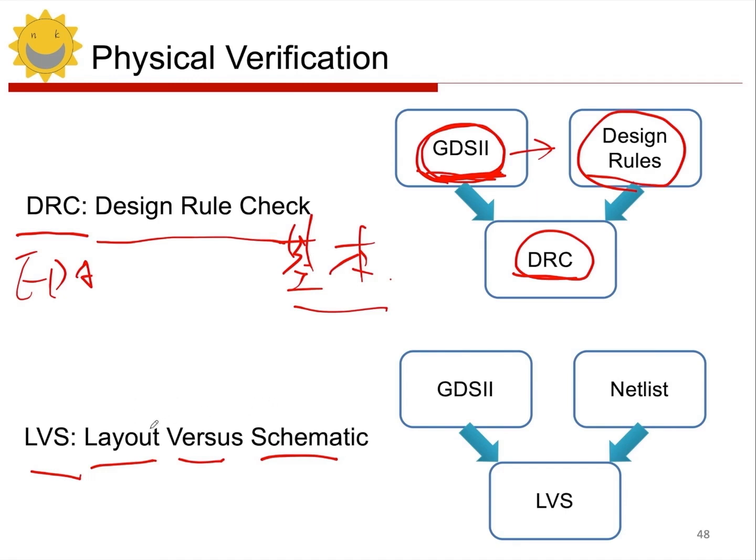However, during the drawing process, you might make a mistake and accidentally connect the gate to the source instead. That would create a mismatch between your layout and schematic, leading to problems. In other words, your layout wouldn't represent what was originally intended in the schematic.